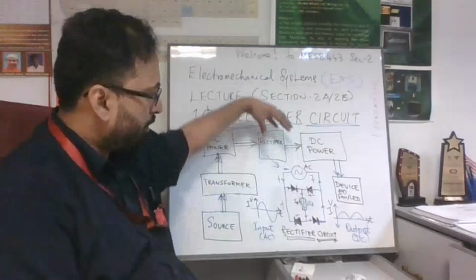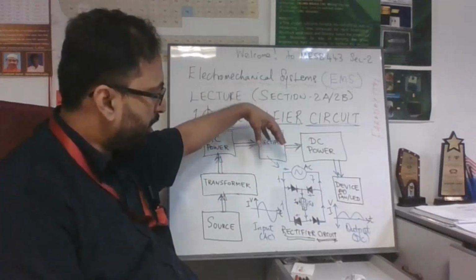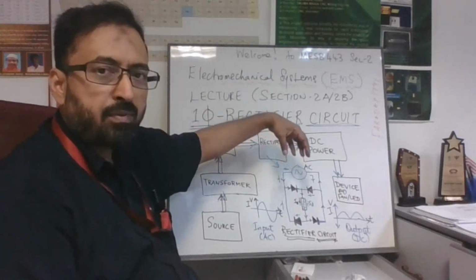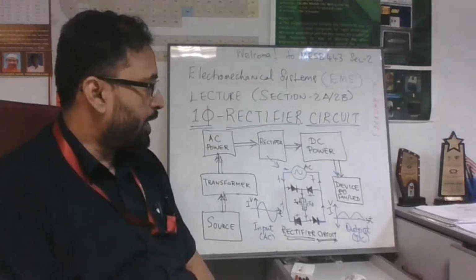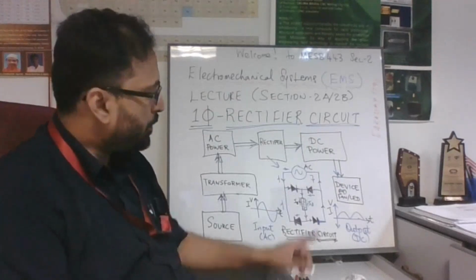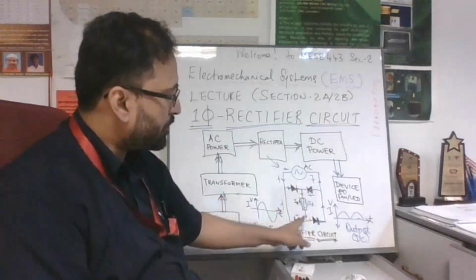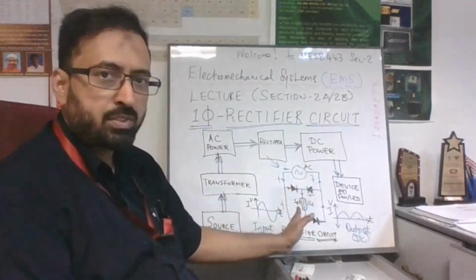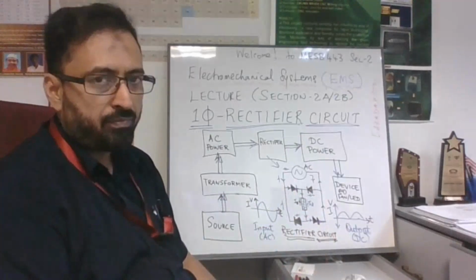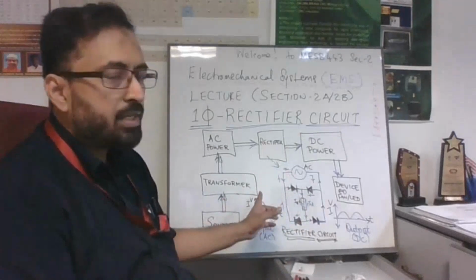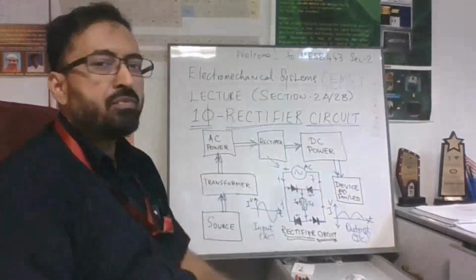So in between AC to DC, the conversion takes place at a device which is known as the rectifier. The rectifier actually consists of some power electronic devices such as diode or thyristor, etc. In this circuit, we are actually going to understand the function of a rectifier with the help of a 4-diode system, which is also known as bridge rectifier. Here the construction of the rectifier based on the arrangement of the diodes looks like a network bridge. Hence the name bridge rectifier. This rectifier circuit converts a single phase alternating current to the direct current. Hence it is also known as single phase rectifier.